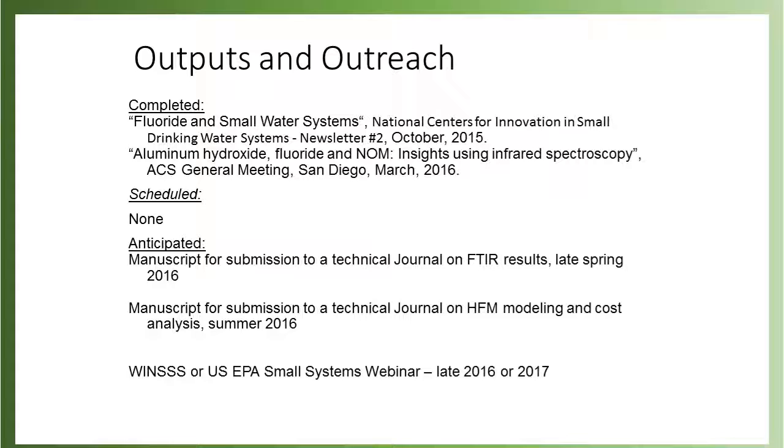Because if you can get NOM removal at that level, disinfection byproducts become, I mean, if you can, in essence, target the divalent there, you do even a better job on the ionic strength. Right. Absolutely. People have looked at it, but it's never really been done. Not necessarily with ED, but with other processes, with ion exchange processes, CDI, mixed processes, as well as ion exchange membranes. The ion exchange membranes that I'm aware of are not very selective.